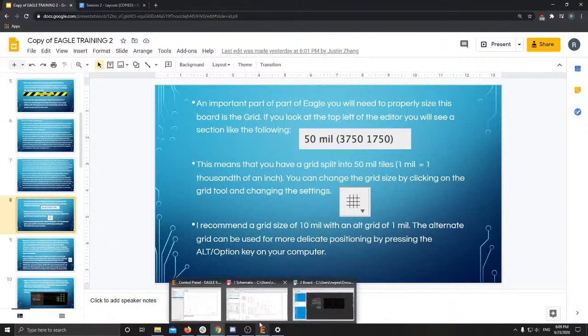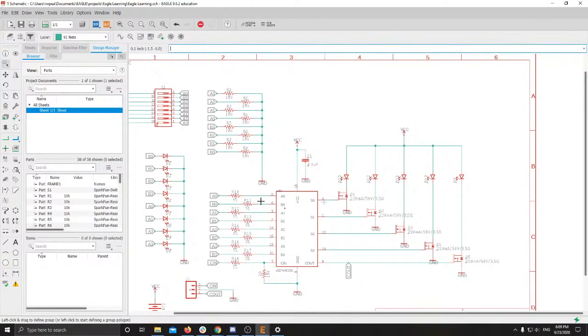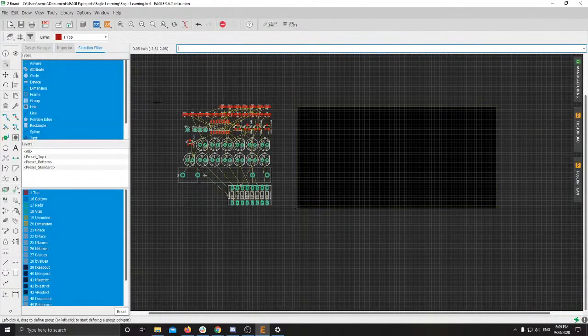So Ed, what you're going to do is if you have the schematic open, you can click this little button right here, kind of in the top left under View and Tools, right below that menu. It's Generate/Switch to Board. And once you click that, it should bring you to this, or it will ask you if that's what you want to do. If you need more help, feel free to just ask in the Discord, and Reed or someone else should be able to help you out.